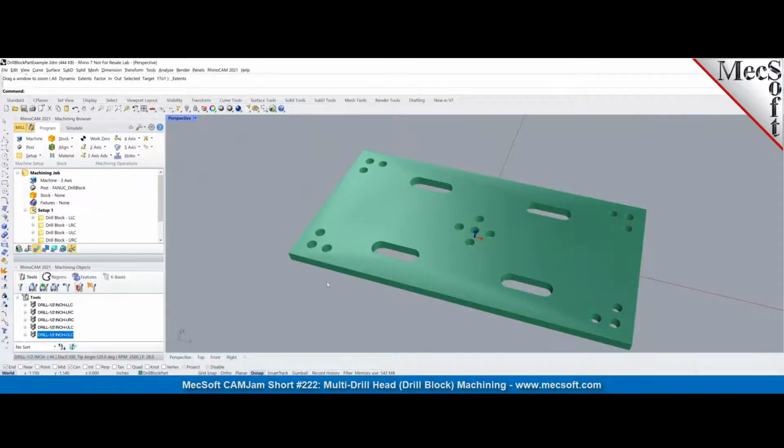Okay, so what I have here, let's talk about this whole pattern on the lower left corner. If I employ my 4 drill head or 4 drill block, I need to turn off drill number 4 in this particular case, because there's nothing to drill on that location. So I would need to turn on drills 1, 2, and 3 in my drill block.